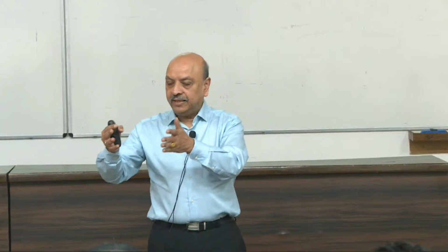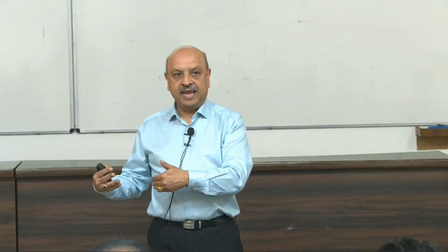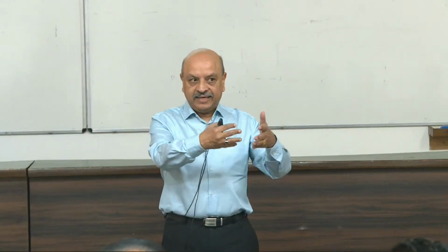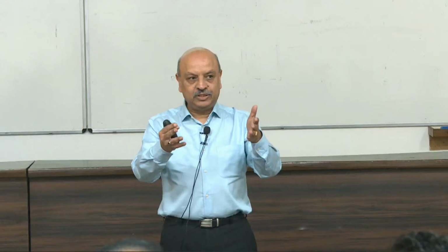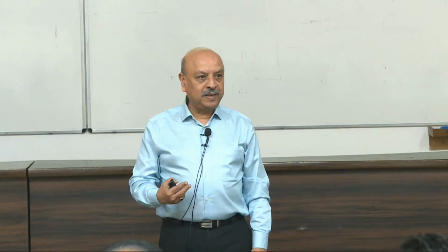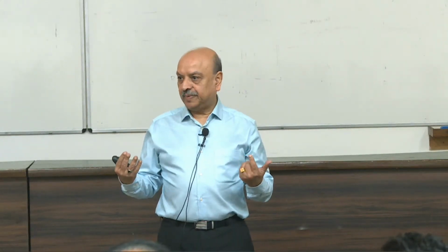So what did we do then? We came to our system A, which is the system that needed the assistance, and we added this new tie line constrained equivalent assisting unit model. We assumed that it is like another generator, and then we added it to our system A. We rebuilt the capacity model, the capacity outage probability table, and then we found the risk, loss of load expectation.